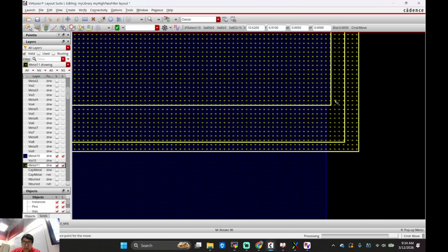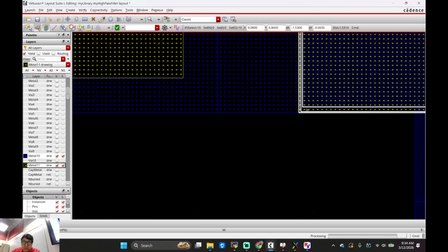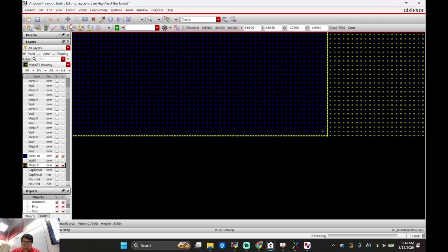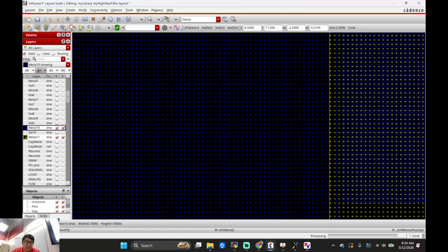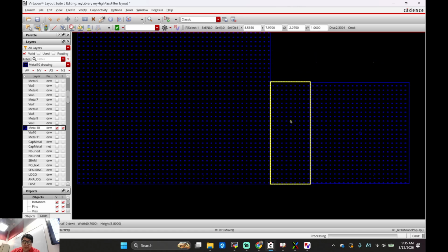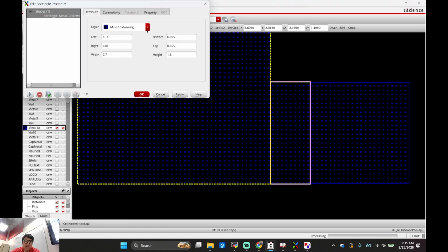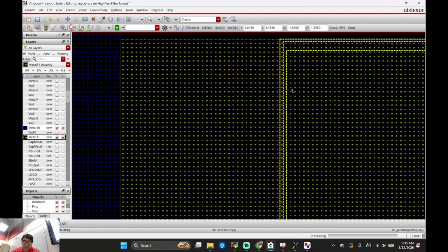Okay, put that right there. So I'm going to do this. Go to metal 10. I want to replace this and change this to metal 11. Hear me out, okay? Metal 11. Boom, boom. So now that's connected to metal 11.